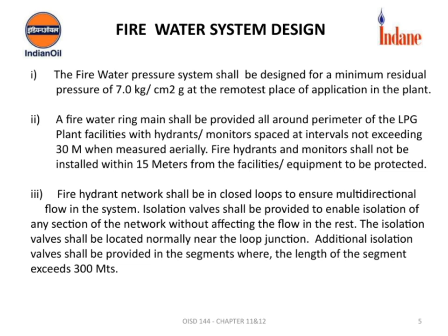Next, a fire water ring main is to be installed all around the perimeter of the LPG plant facilities. This ring main acts as a backbone for the fire water distribution network. Hydrants and monitors are to be spaced at intervals no more than 30 meters when measured aerially. This spacing ensures adequate coverage for fire fighting.